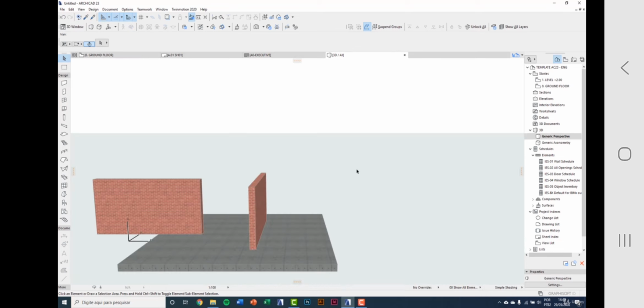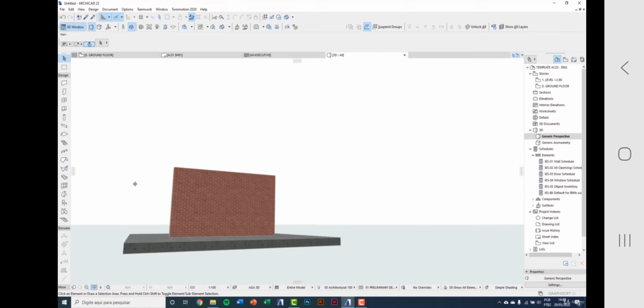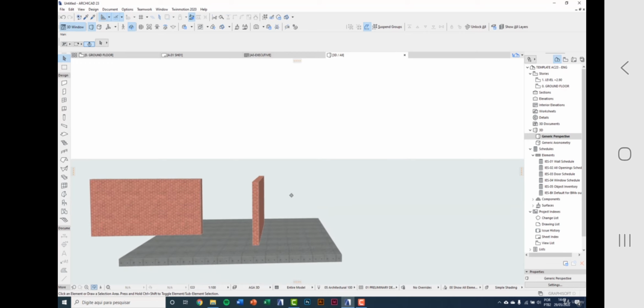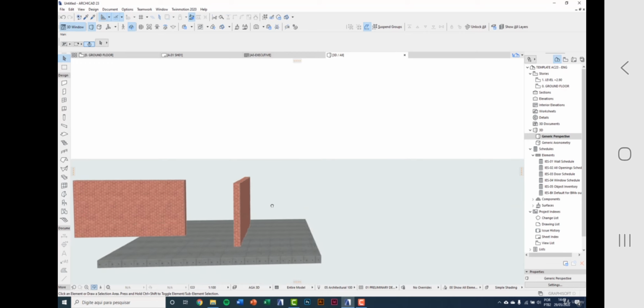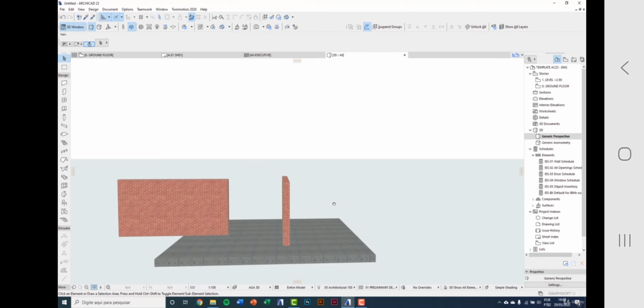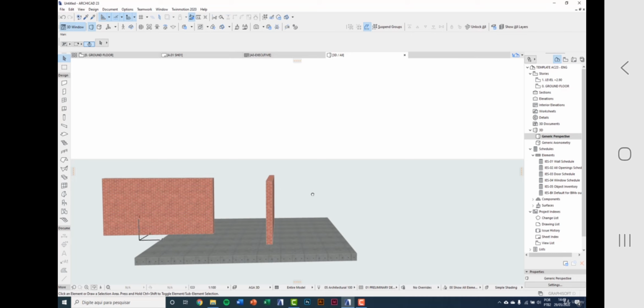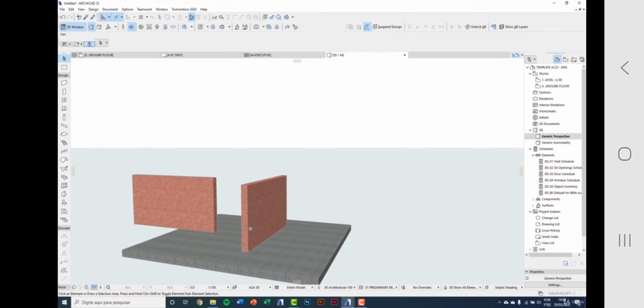On 3D there is the orbit command available in this bottom bar. Here I have orbit. And using orbit you can click with the left mouse button and rotate. Pressing the mouse scroll you do the pan, dragging the model. Another option to use the orbit command is using the O key. So pressing O, you have this shortcut to the orbit command.